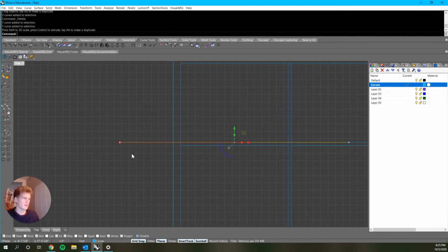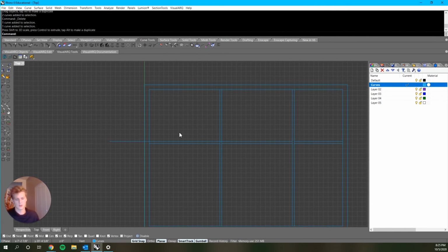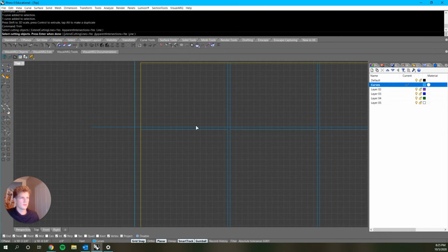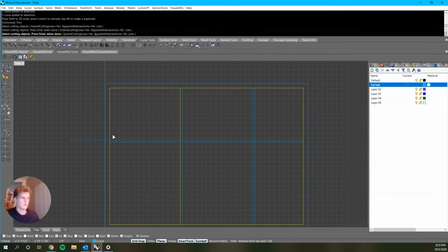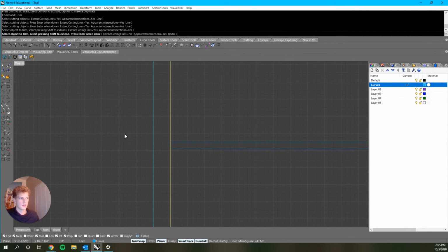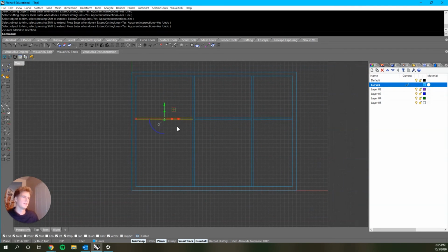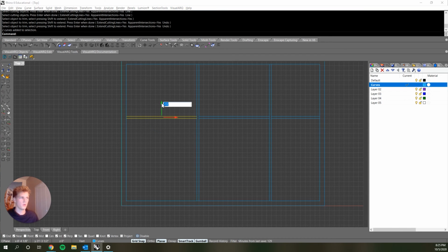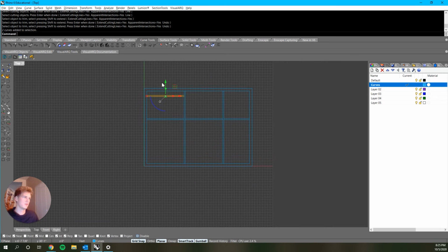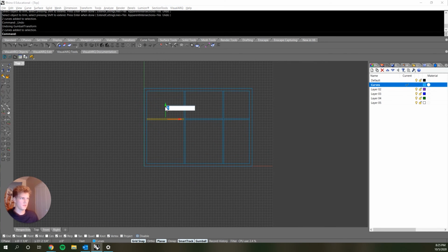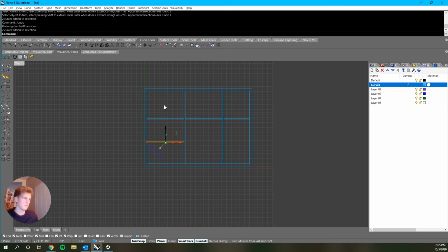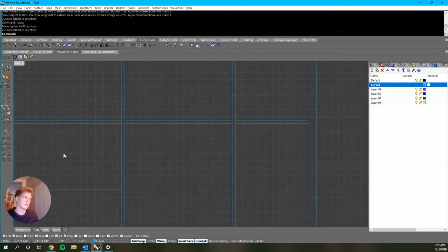If one of these lines projected beyond something that you didn't want it to, you could use a trim command, type trim, and you could select the cutting objects there, and maybe that one too, hit enter, and then choose to cut that one and that one, right? So that's another way to get that. And if you wanted this wall to be a duplicate down below, at let's say like a 9-foot room or something, or above, you can just hold Alt, click the arrow, -9 feet, enter, right? And you can start to get an idea there.